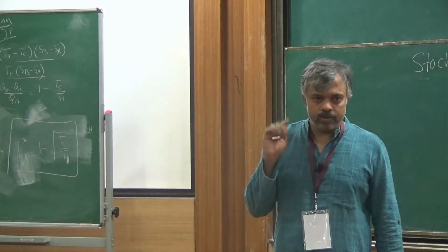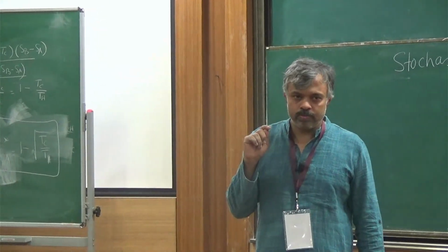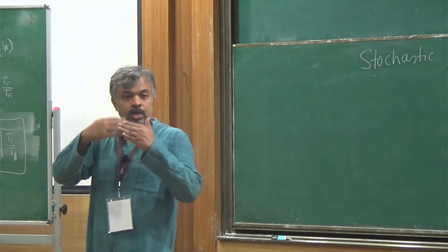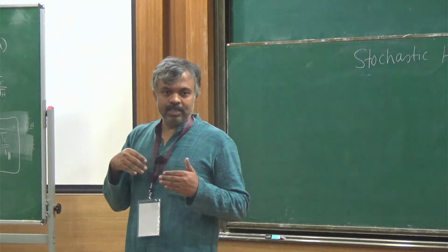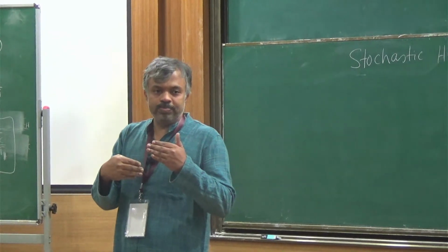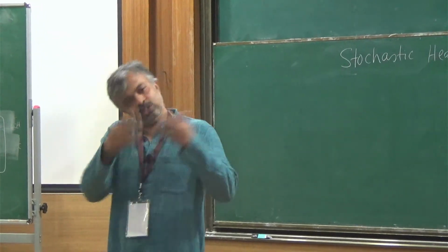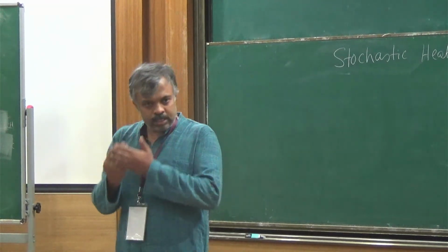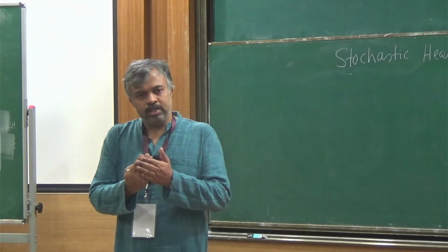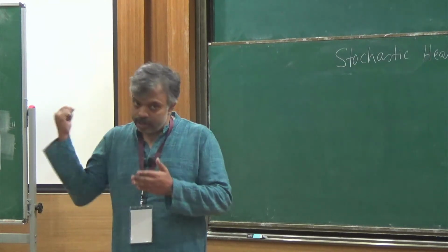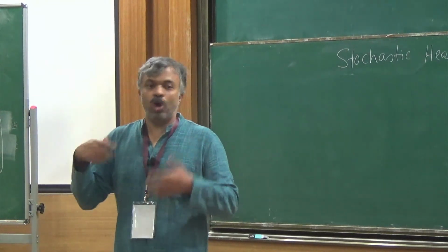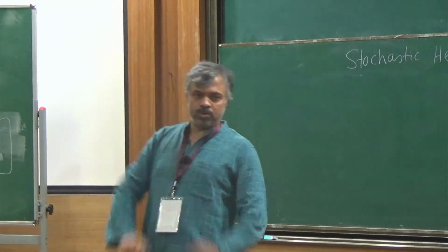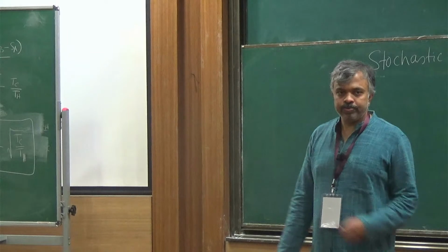But for the Carnot engine it is also 0, right? For the Carnot engine we don't have a temperature difference between the bath and the system. It has to be 0 because the bath temperature and the system temperature are always the same. They are in equilibrium. But here it is not, so it is not obvious that the change of entropy has to be 0 over a cycle.